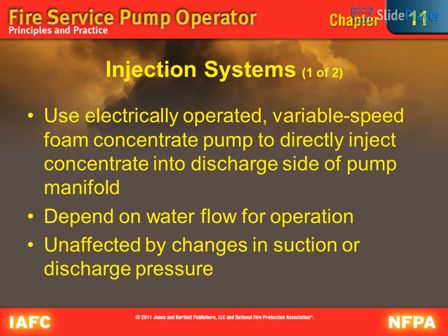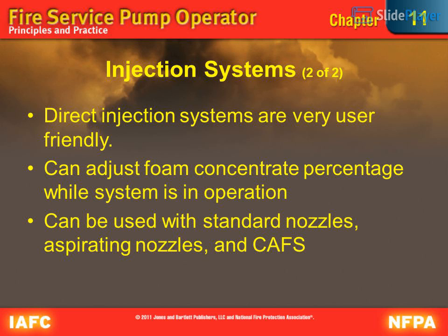Injection systems, 1 of 2. Use electrically operated, variable speed foam concentrate pump to directly inject concentrate into discharge side of pump manifold. Depend on water flow for operation. Unaffected by changes in suction or discharge pressure. Injection systems, 2 of 2.